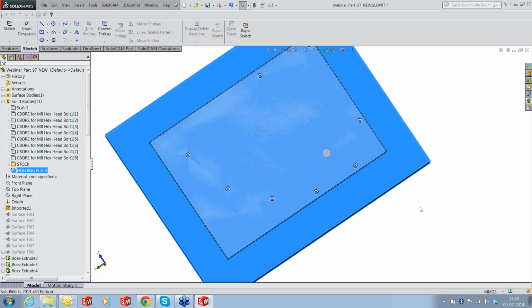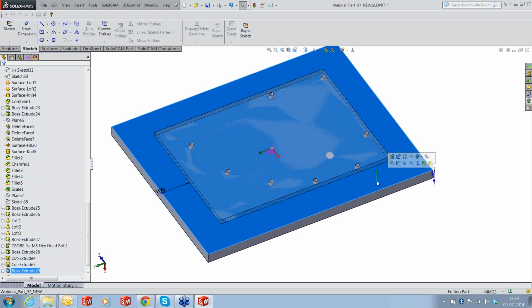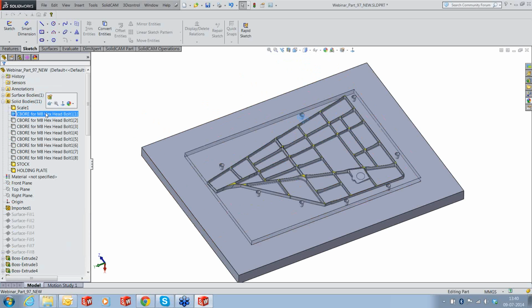holding plate. Now this holding plate has a couple of other features. This holding plate will also have a pneumatic holding. It will be holding using vacuum. So we have got about 7 to 8 screws, first of all, holding the block down on the part. And the entire thing is then being held on the bottom plate, and then there's a vacuum that's actually holding the whole thing down, so that there are no warpages as such on this particular part. Having said that, I've got the lugs and the main part.